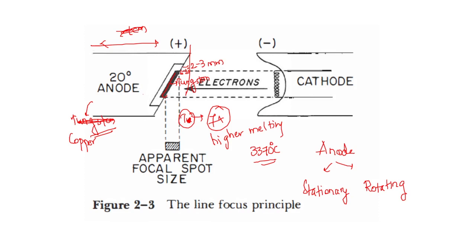area. The tungsten is bonded to a copper here. If you see, the copper is a good conducting agent. Because it is a good conducting agent, it can dissipate the heat towards itself. It can absorb the heat from the tungsten, because copper is a better conductor of heat. So as a result, because of the good thermal conduction capacity of the copper, and this copper is made to be a larger block, it can increase the speed of cooling.